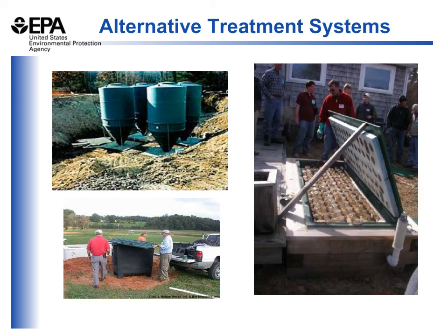So we've talked about the traditional septic system that includes the septic tank, the distribution box, and some sort of dispersal field, including the various examples we've just gone through. It is also important to note that there are a variety of different alternative treatment system components that can be added to a septic system to improve the quality of the water that's discharged through the leach field and down into the ground underneath. This is often done to help protect drinking water wells, coastal waters, or freshwater lakes or ponds from the effluent that's discharged from the septic system.